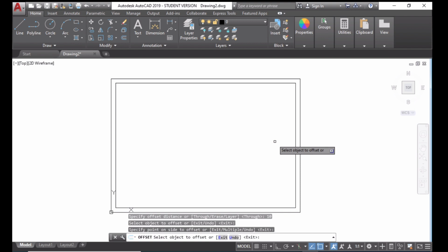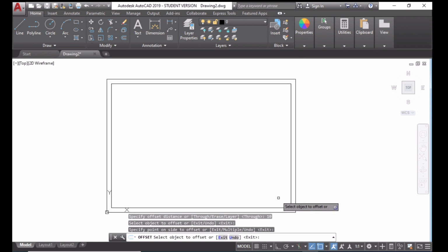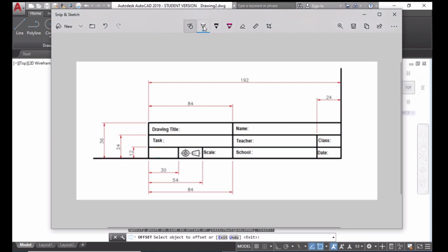We almost set the template, but based on your requirement, we usually make a title block, with some details like the name, the title of the drawing, etc. If you want to make that kind of information, you can construct a title block on the bottom right corner or whatever position you want. Let me show you one standard title block right here. You can see I have the information like how much length you should have, what is the width of this title block, and the geometry for each and every cell.